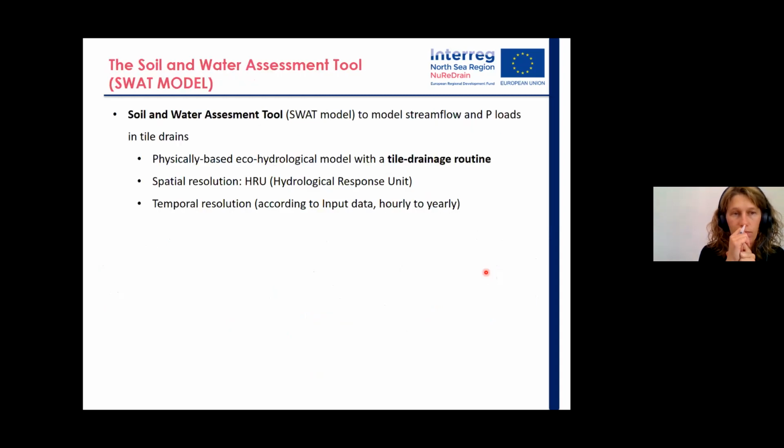The modeling we did was done using the Soil and Water Assessment Tool, which is called the SWAT model. And we used it to model stream flow and the phosphorus loads in the tile drains. The SWAT model is a physically based eco-hydrological model with a very sophisticated tile drainage routine, which makes it particularly suitable for our watershed of interest.